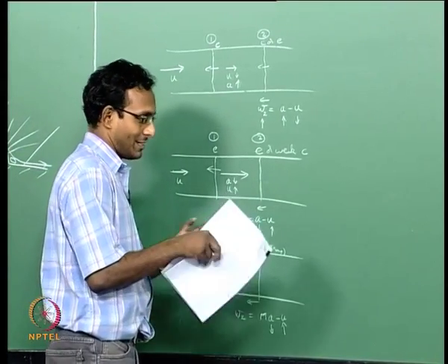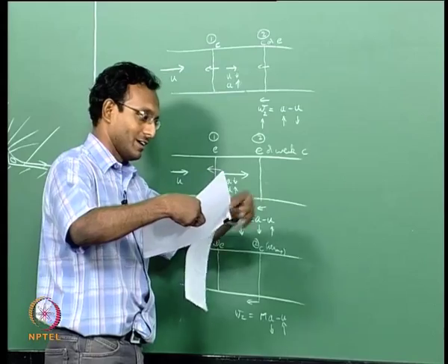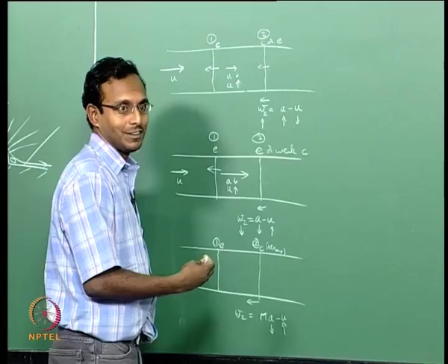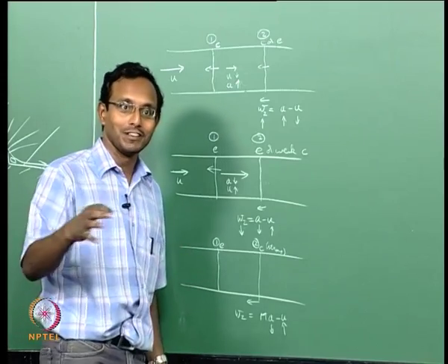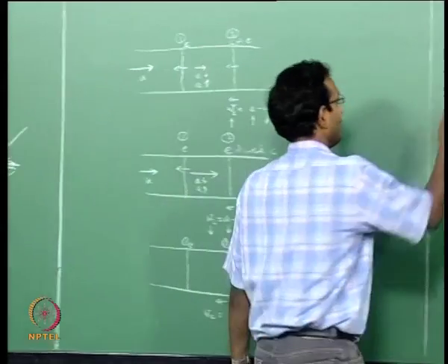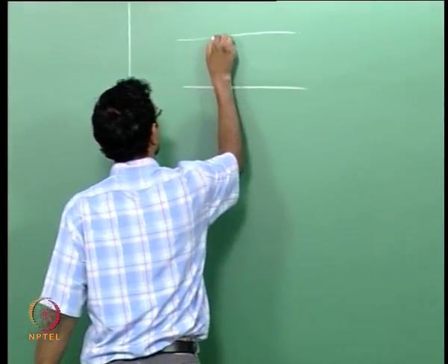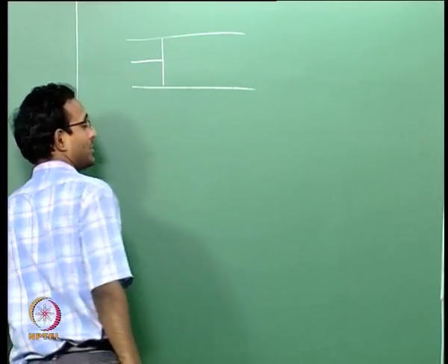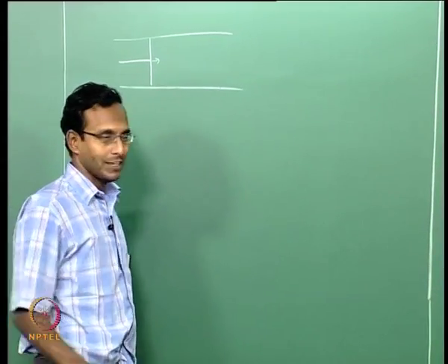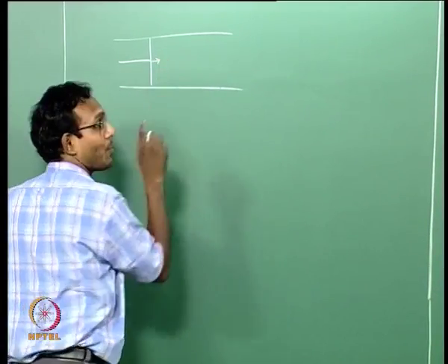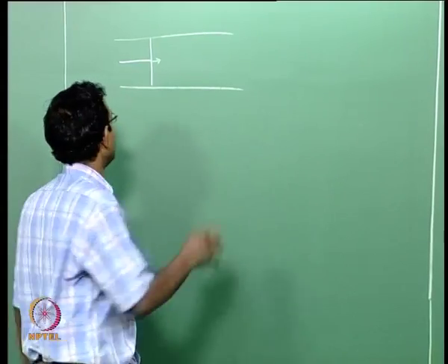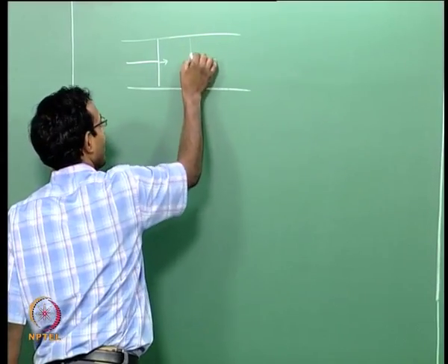Okay. Once you know all this, now we will go back and look at the wall moving case. Now I can tell for sure what will happen. We already told this once, I am just going to repeat it here because this is unsteady flow discussion. So, if I had a condition where I have a duct and I have a piston, and if the wall is moving into the fluid element, then every point on the fluid element will create a compression wave. Now, since I am thinking 1D, I am going to get a 1D wave.